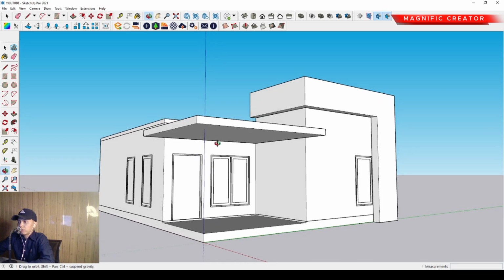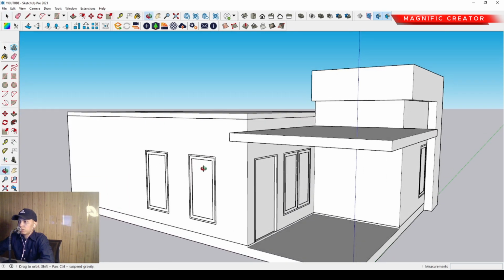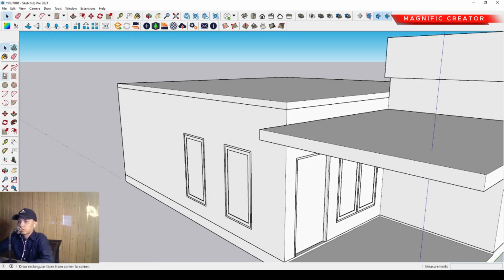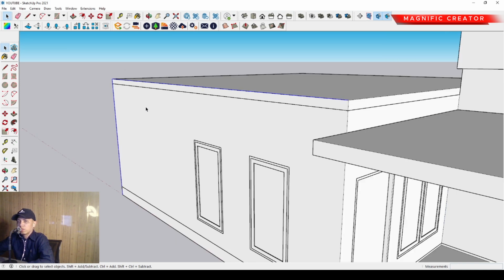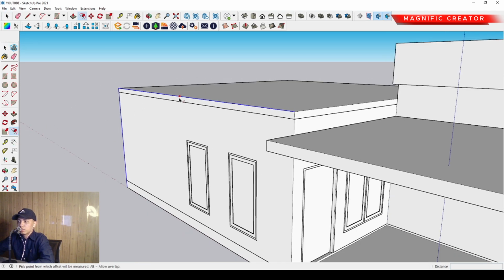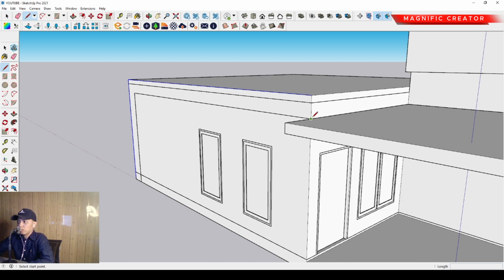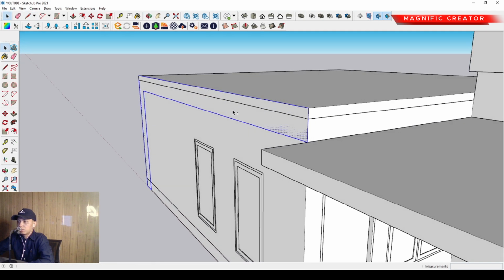And after that, we can also make another shape of this concrete wall here. We can use this line. We can start from here through this corner and end on this bottom corner, and just click off both of the elbow lines, and then we can offset it inside around 477 millimeter, and we can close every single uncompleted pattern, the basic pattern of this additional concrete.